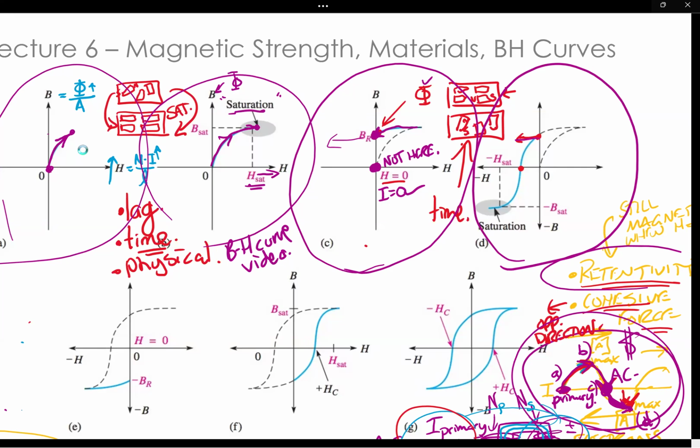So here we go with that coercive force in D. I put this much current in, I go down to 0, and then I put the maximum amount of current in down here. I am now at the very bottom of an AC sinusoid right here at D, and I have I max in amps in the opposite direction.